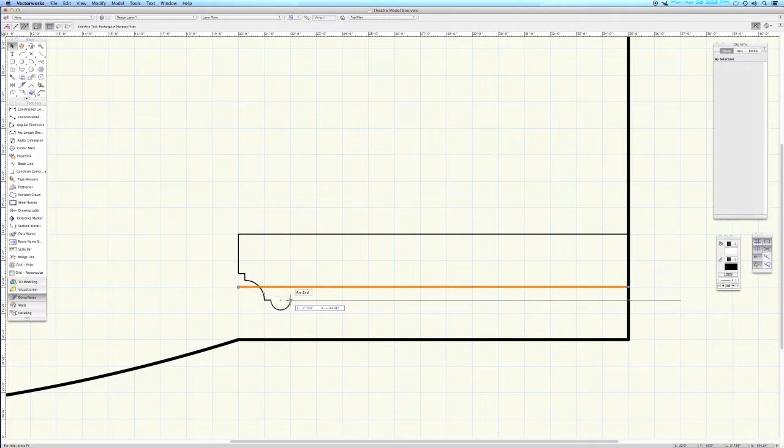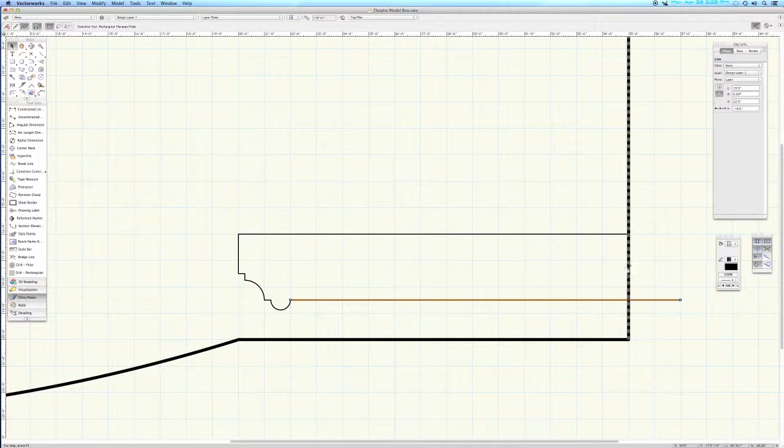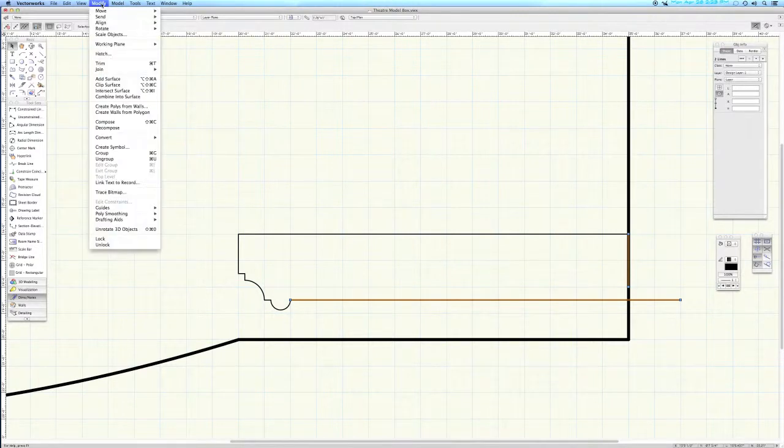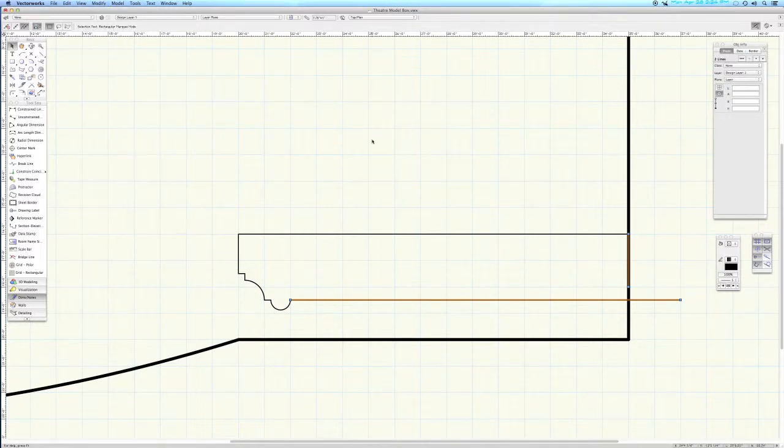I'm going to drag this line over, connect it to that. So with this line selected and the other end line selected, I'm going to connect these two lines, and that's my right clicker on my mouse. I have programmed to do Command J, which is join. You can see join is Command J. So with my right clicker, I can connect those two lines.